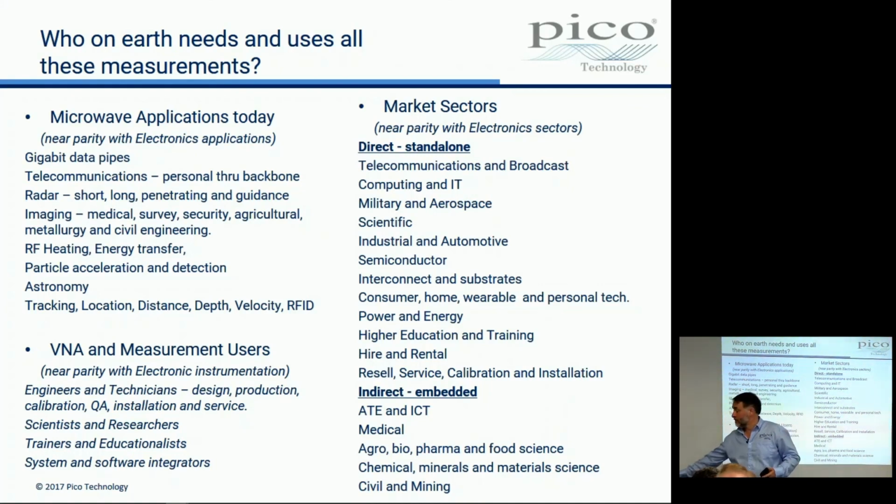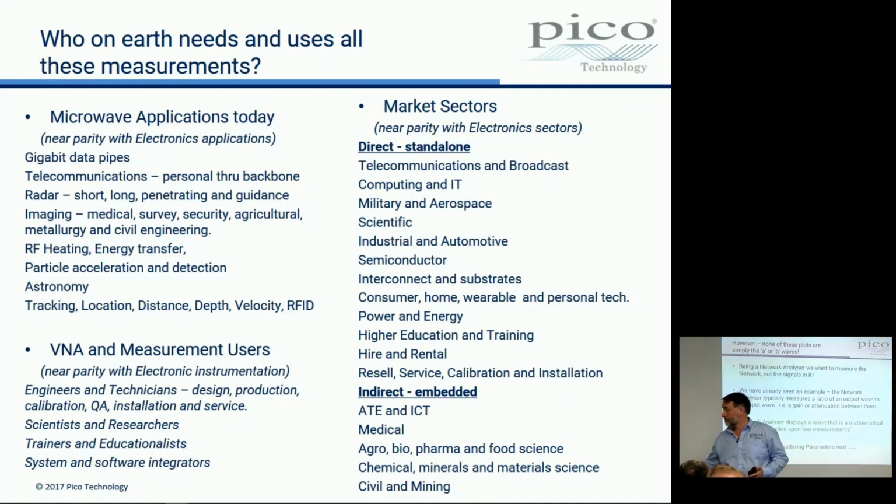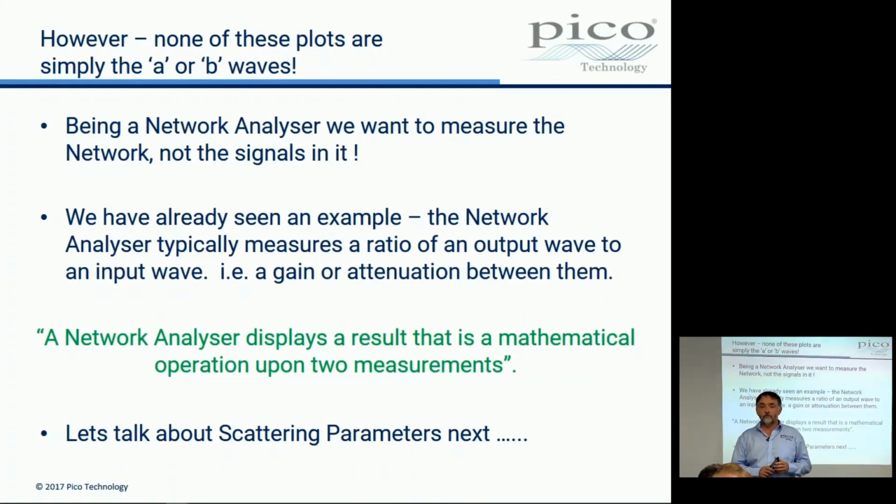As we know with scopes, a large number of our customers build scopes into their kit and it becomes a part of the system. So is that just the same with VNAs as well? Yes, VNAs are quite regularly built in. VNAs are also called reflectometers. A reflectometer only has one port and it only measures S11. But that often is the only measurement that you need.